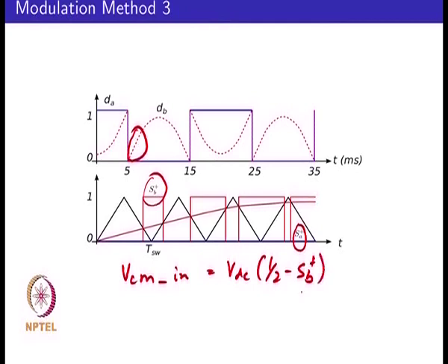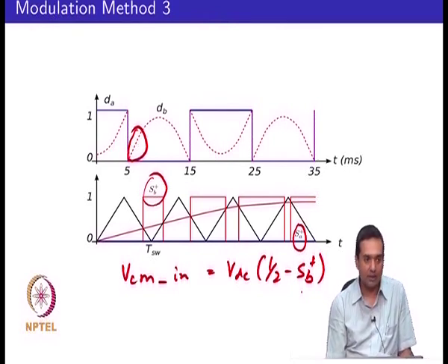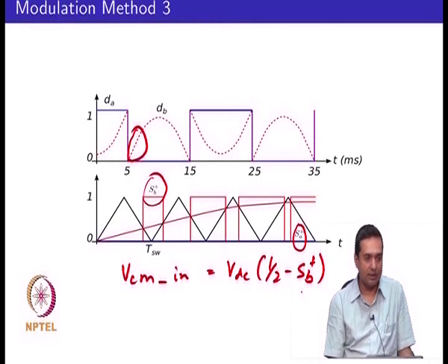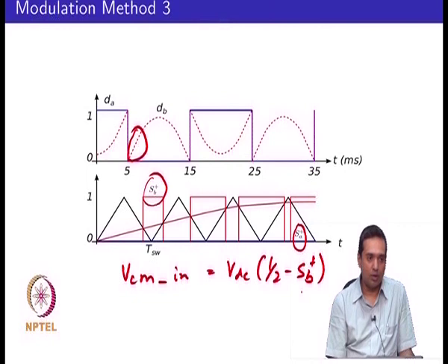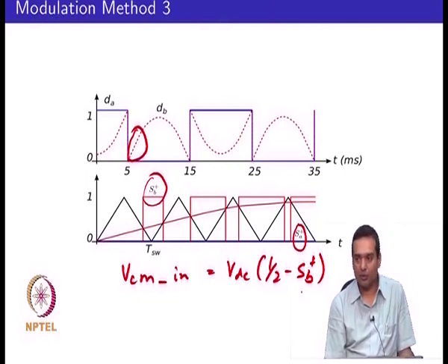In this case, we can see that your input would see high frequency on the common mode. So, we have problems with the high frequency on your input side. You also have now only FSW as your output equivalent switching frequency, which means that we lost the advantage of 2 FSW.